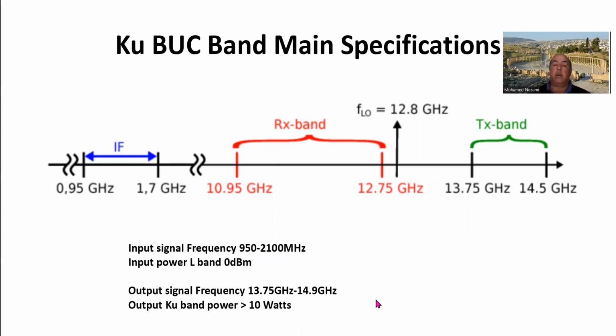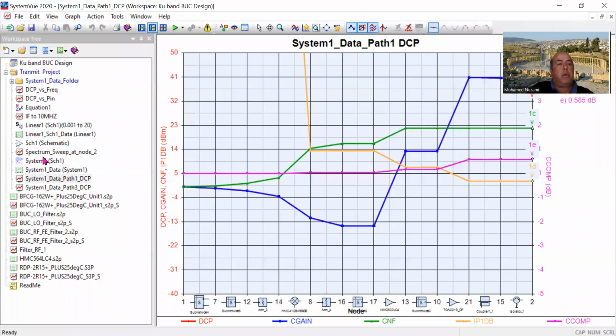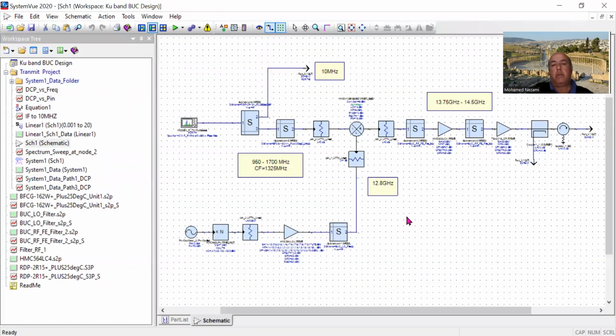And utilizing the technology of GaN, gallium nitride amplifiers, okay? The reason for that is because the design is much simpler, given the high power density of GaN devices compared to GaAs. We're going to end up with a small size and a lower number of devices to build up the power level to 10 watts. Okay, so here's the system that we have today, just to skip ahead to what we're going to be talking about. So I put up the system in here.